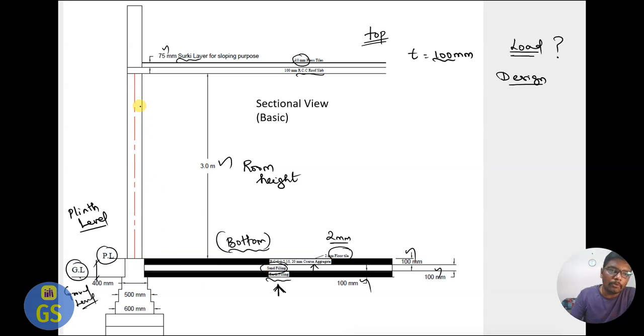And now the most important thing, you can see the center line. This we call the center line, which is part of your column head. Your loads are going to transfer over this. From here, the loads which come from the column are going to spread on the footing, it is going to get dispersion. So that we call dispersion, it is going to spread. So this is how the building is done. From the column the loads will be distributed.